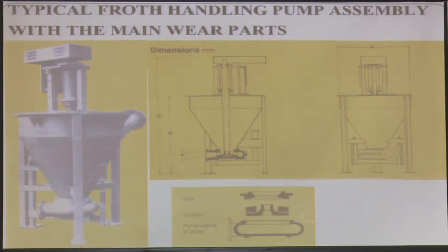Froths with 100% flooded suction, and it used to also get some ventilation point so that the froth air can be released, and the inlet used to be like this, impeller like this, and the pump casing like this. Normally those are the rubber lined froth ones. Duty wise, light duty, not a very heavy duty one.